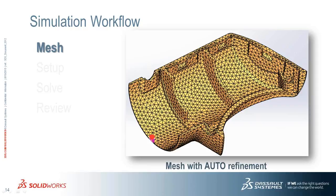So in the first step, one would start with the mesh, and SOLIDWORKS offers auto refinement and auto meshing capabilities just to speed up the process. As mentioned earlier, SOLIDWORKS Plastics is more of a designer-friendly tool, so it helps a designer set up a simulation quickly and not take days together, and run the solution and go back and make design changes back and forth in the early stages of the design.